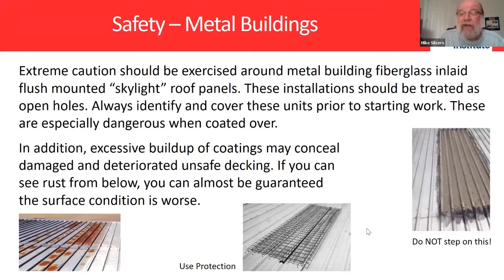Preferably, if you're going to coat the entire roof, pull those skylights out and replace them with metal and eliminate that fall through, because there have been some very serious accidents where people unknowingly stepped on those skylights and went right through. So keep that in mind. And even if your boss is asking you to do it, you might want to bring it up and say, hey, are you sure this is a good idea, before you actually do so.